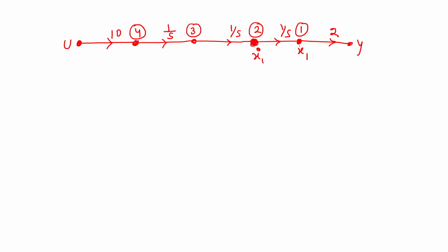The forward path is an integrator, so on the backside it is differentiation, right? So the differentiation of x1 will be x1 star, and I always assume that x1 star is nothing but x2, right? If this node is x2, then what is node 3? It will be x2 dot, right? If x2 dot, what do you have to assume? x3, right? Then if this is x3, then what is this? This is x3 dot, right?